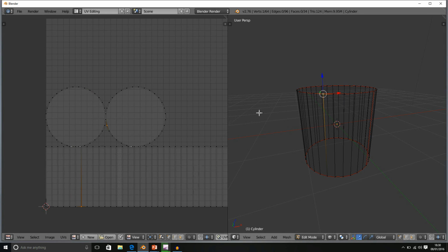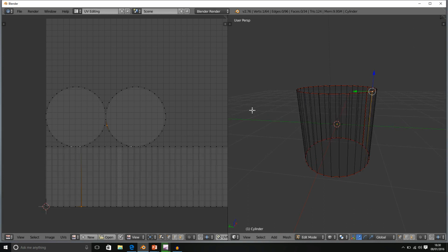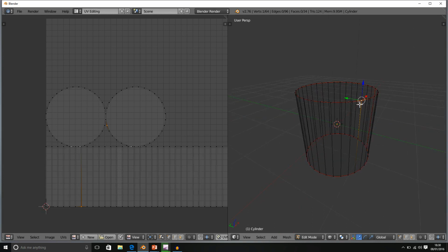Make a note in the UV editor when it comes to vertices that if a vertex joins more than one face together, which it normally will, or if it joins more than two faces together, that vertex might be duplicated when unwrapped. But this is not really a problem, as the main focus when unwrapping UVs is to make sure all of the faces are correctly formatted.